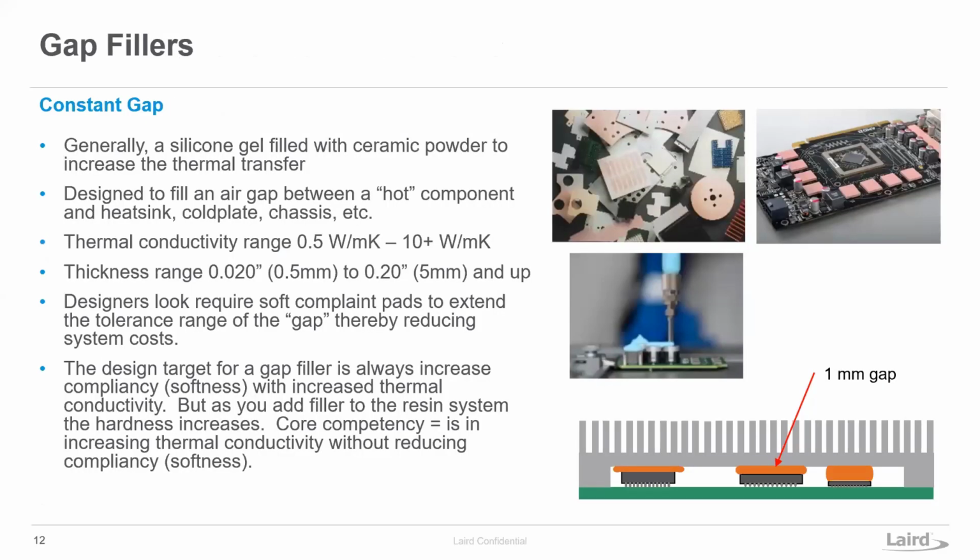Next product family is the gap fillers. Gap fillers replace air for the most part in large gaps. They heat or cool multiple components to one heatsink. That's the general application, which you can see in the bottom here, where you have different thickness gap filler pads cooling different size components to a common heatsink.